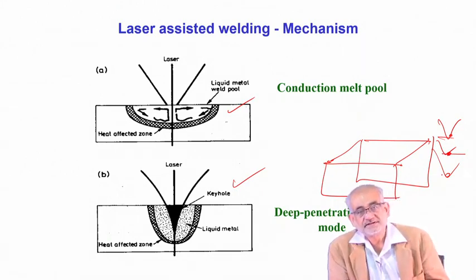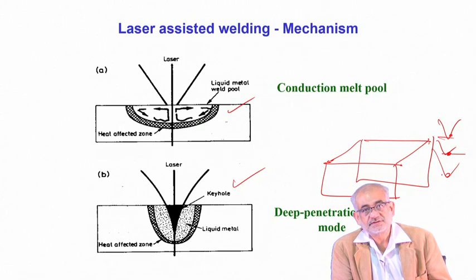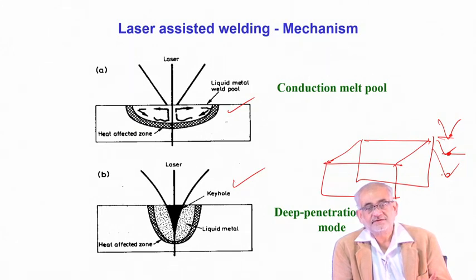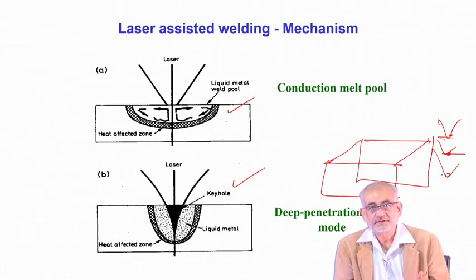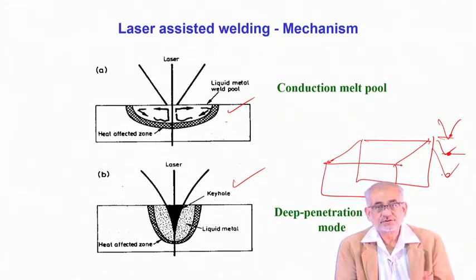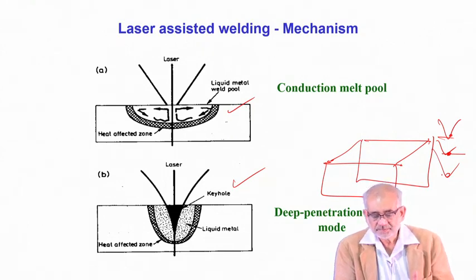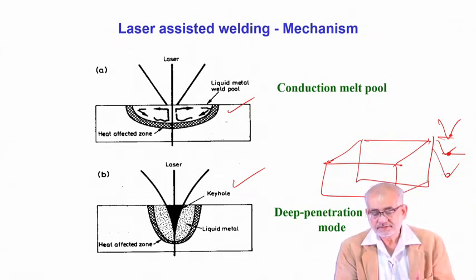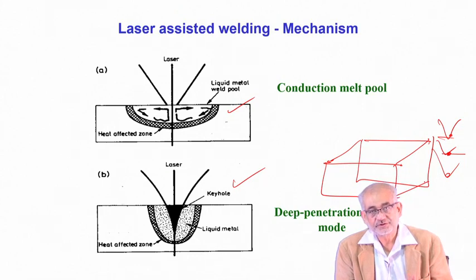One of the biggest advantages of laser material processing is that you can do it either in a controlled atmosphere in a confined chamber, or if it's a non-reactive metal, you can easily do everything in open air. You can also process where you have a very high melting material on one side and a low melting one on the other, so you have to have a correct strategy of joining them. But you can certainly use laser for joining.